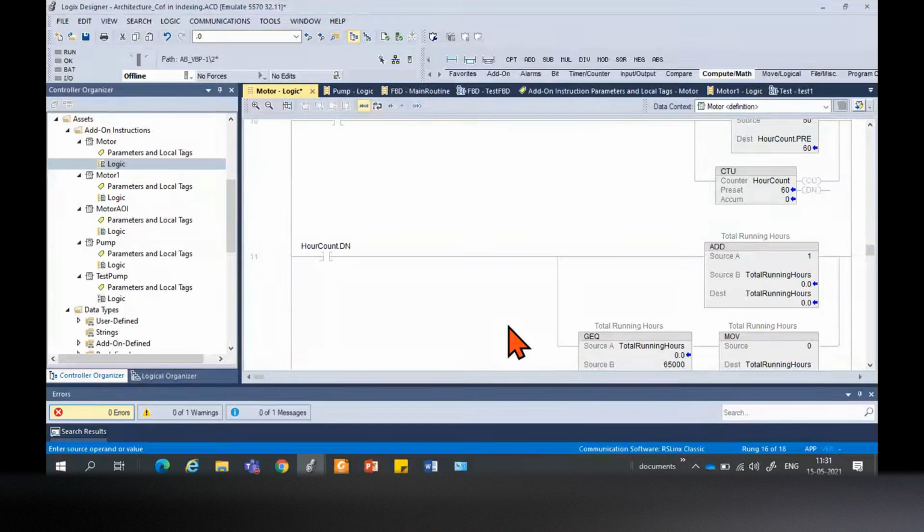If we remove the battery of the controller, then it is stuck with the default time, and when you start that controller it starts from the default time if there is no battery for the controller. And if it is synchronized, then it is not required to set the default, it automatically synchronizes all the timers.